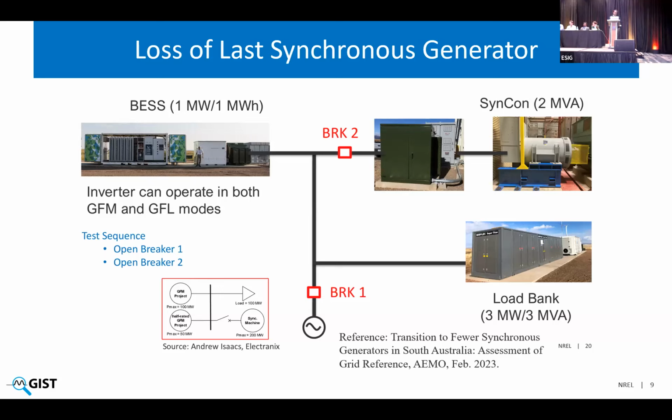So in this particular test, the island test, what we did is first we removed the grid simulator, or removed the grid, to see how the inverter, synchronous condenser, and load together balance the grid and supply this load. And in the second stage, we removed the synchronous condenser to see if the inverter is capable of maintaining this island grid or not.